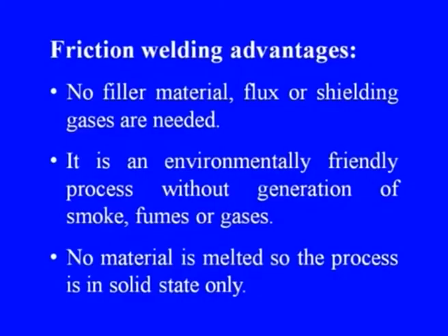It may reduce the joint strength, or it may change the metallurgy of the joint, or other mechanical properties or electrical properties of the joint. Therefore, here no filler material is used. So, the material properties, the strength properties, etc., will remain those of the original materials being used.